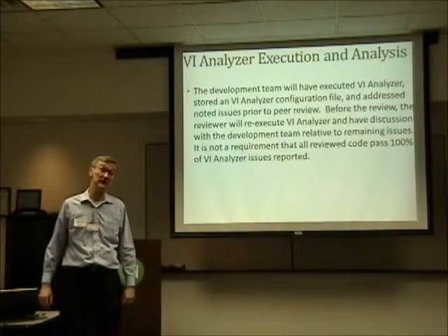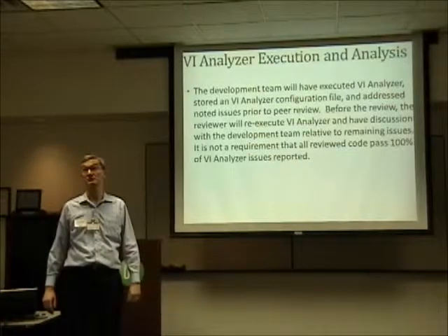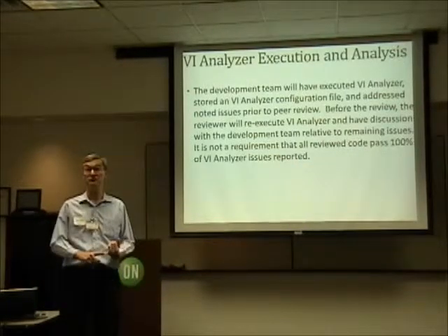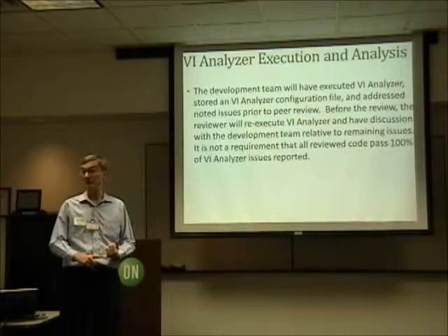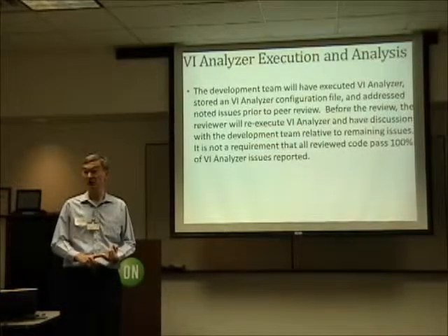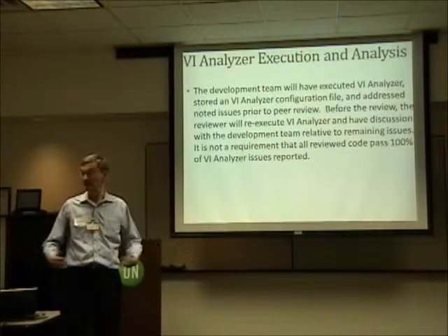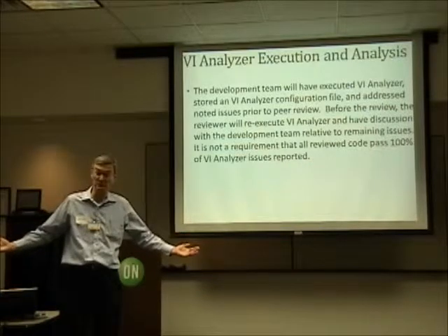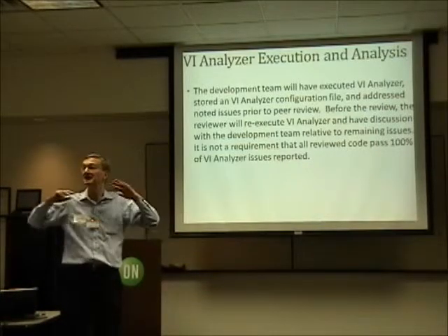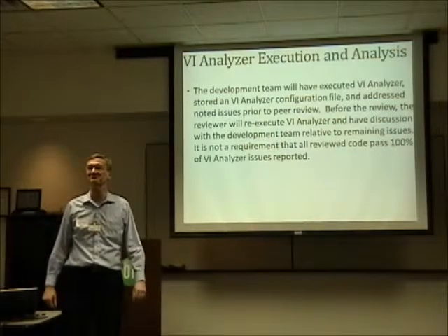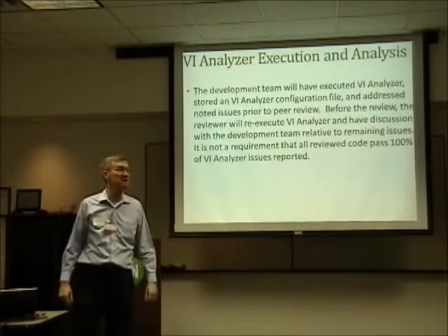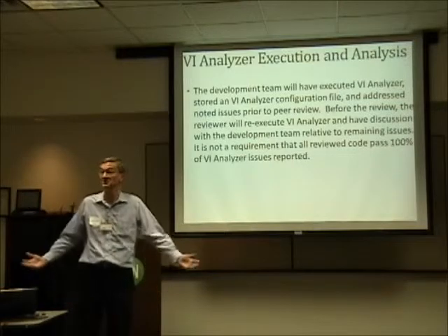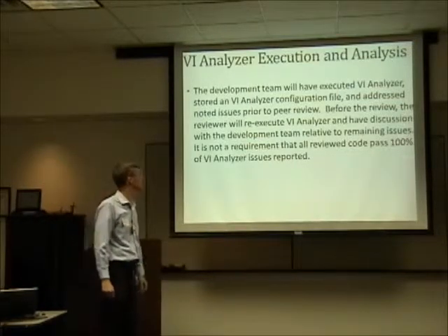The one thing I will mention about VI Analyzer is you really have to customize the rules for your own environment. For example, there's a very fine rule in VI Analyzer that looks at your front panel and it wants you to use all dialog controls. There's a reason for that. If you put your code on a Macintosh or put your code on a Linux machine, it will look like the native operating system. Well, we work for a large company. All of our testers have Windows-based computers. I turn that rule off. I could care less what my code looks like on a Linux machine. You may not have that luxury. But I turn off any rule that's associated with that kind of stuff because it doesn't apply. It applies to somebody but not to us.